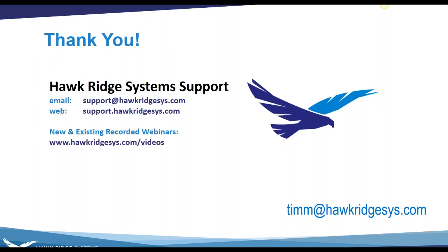I see one question asking about runtimes in comparison to SOLIDWORKS Premium. It's tough to do an apples-to-apples comparison, but for this class of contact problems, you have a lot of controls for things like penalty stiffness and the increments that your solver takes that make it possible to tackle problems that I believe you couldn't in any other expert level software.